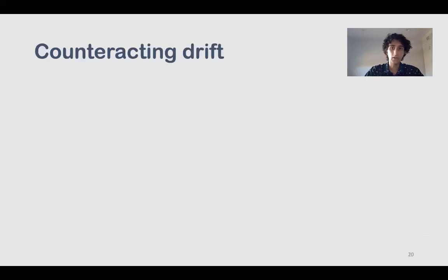Counteracting drift. We measure the fall time of the test button output in order to come up with how much drift is in a given phototransistor. The purpose of this is to apply gain to the phototransistor output. If the phototransistor is drifted, its output is lower, so we can just multiply its output by some factor in order to increase it so that it approximates the behavior of a working phototransistor again.